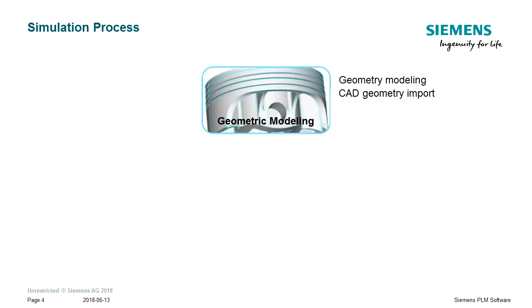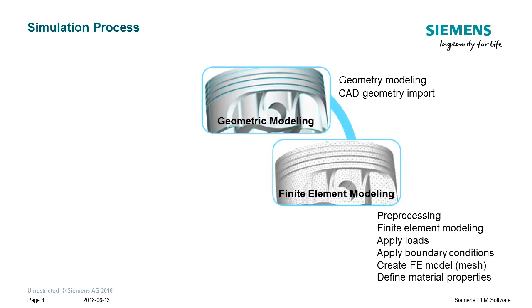It's important that analysis keeps in step with design, where it can have the greatest effect on the design process by showing whether a given design is up to its intended job or not. So time is really of the essence as far as simulation is concerned. Typically, the simulation process starts with model geometry that has been created in a CAD system. To take advantage of this design geometry, the CAD model data has to be transferred from the CAD system to the finite element modeling environment. Once the CAD data has been transferred successfully, work can then begin to create the simulation model.